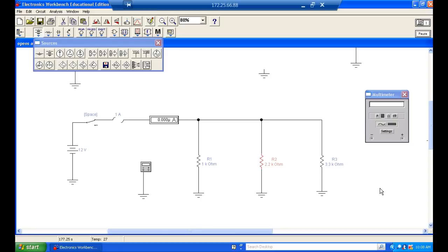Now at my terminal, I have an R. It gets hot. Copper. What happens to copper when it gets hot? Well, it oxidizes. Rusts real fast. Copper oxide is an insulator. Now I've added more R. I push current through R. It gets hotter. Now all of a sudden it exceeds the heat rating of my insulator. My insulator gets charred. It starts burning off. Then it touches something else, and now I got a short circuit.